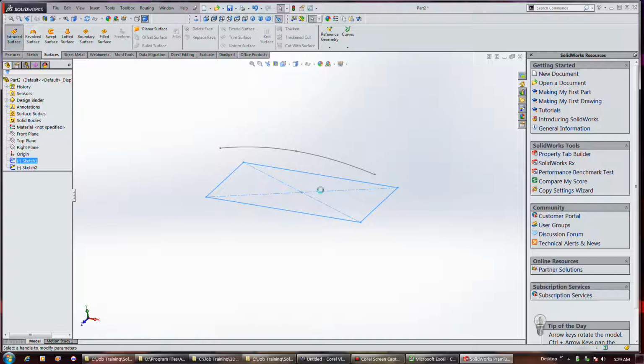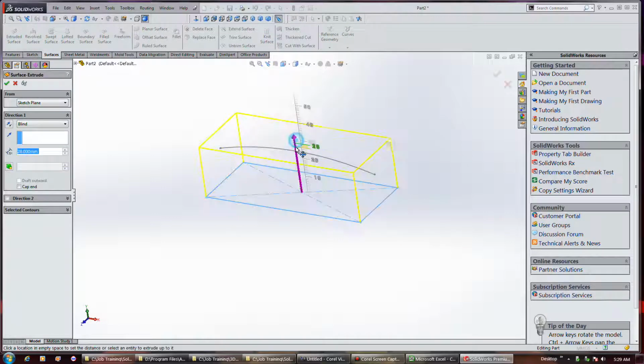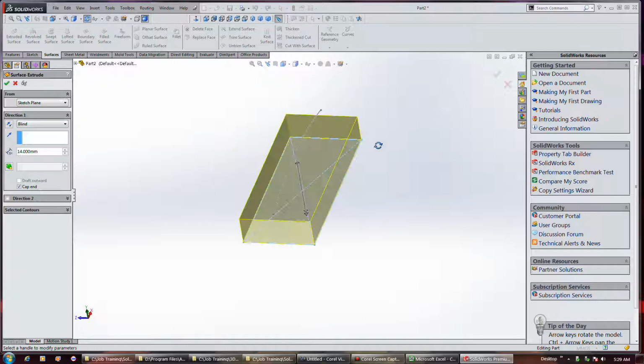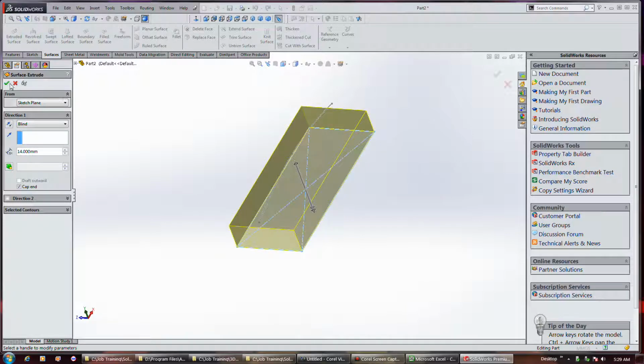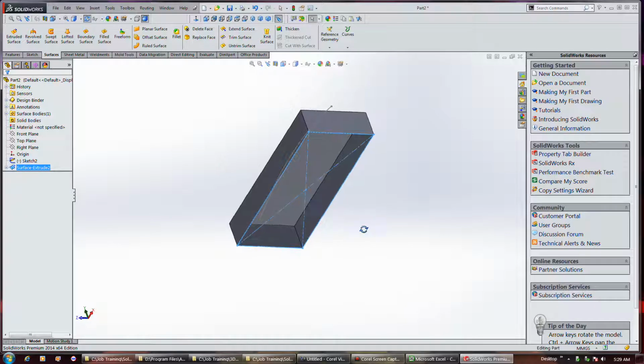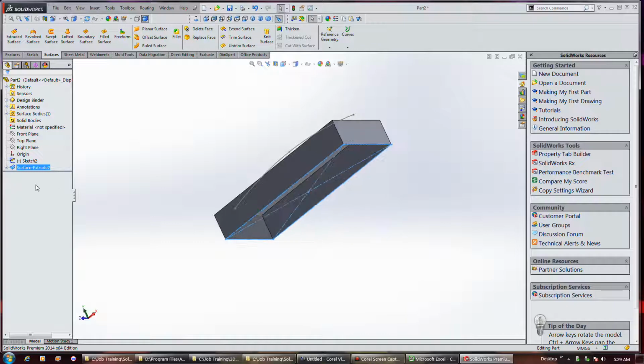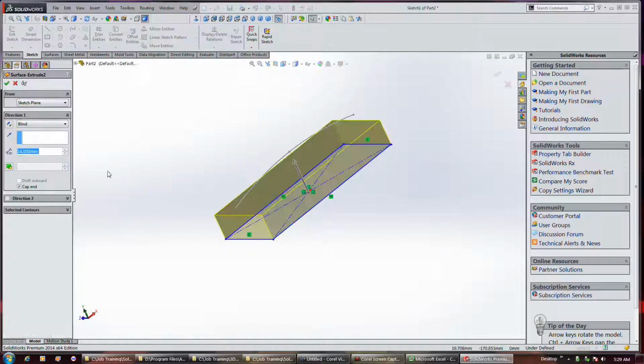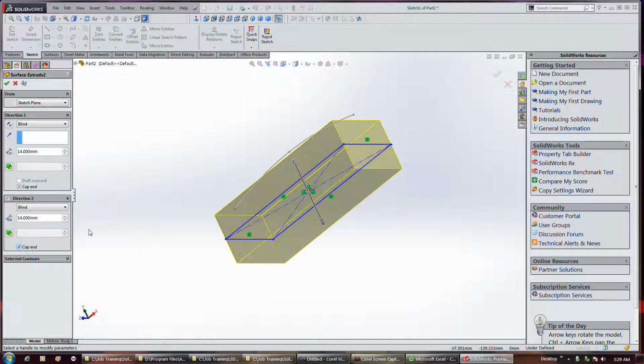At any rate, let's say you have something selected now, you can form a box and you can cap the end. But if you do and hit OK, the bottom of the box is open. But you can go to direction 2, OK, and cap the end.